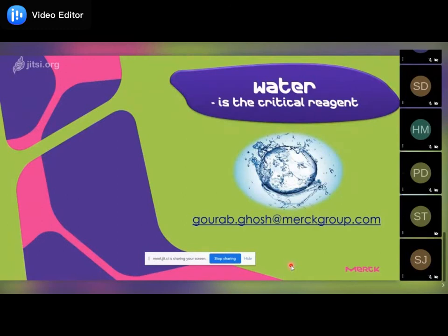Very good question. So thank you to the person who has asked it. Here the thing is that it's not always fulfilling our need. The purpose behind it always talks about TDS control. If you put it by default as a TDS control, sometimes you can see changes happening in your drinking water. If you can really feel changes in the drinking water taste, then definitely some problem is happening. If you continuously monitor that particular factor, it will fulfill your need up to a certain extent. But without monitoring, if you just keep it and assume that you are drinking RO water with TDS control, probably it is not going to suffice your need. The moment you understand there is some deviation in the taste, please adjust it or call the vendor for adjusting it. So there is a real good concern over there.